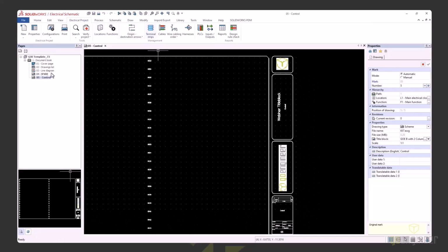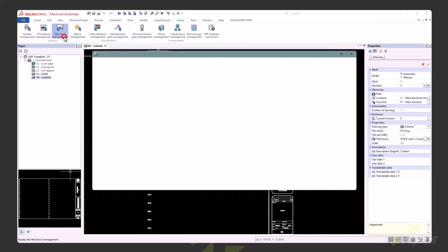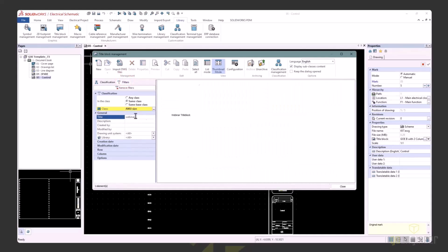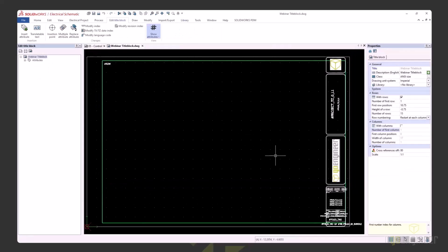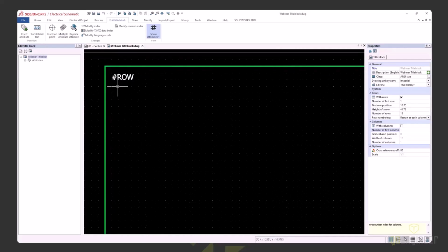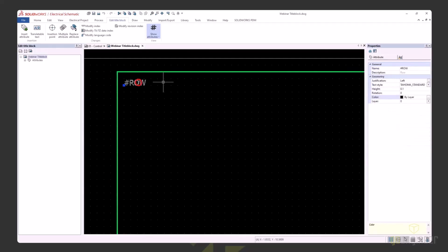But we're working on our title block. So let's go back into library and let's find that webinar. So again, filters, and I can simply type in webinar and find that title block. Double click on it, even if it doesn't have a thumbnail, and notice that everything came back now. All right, so now I can see those grid points a whole lot easier.